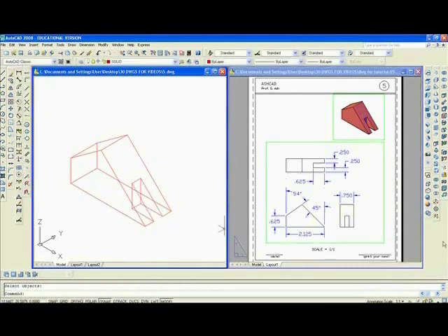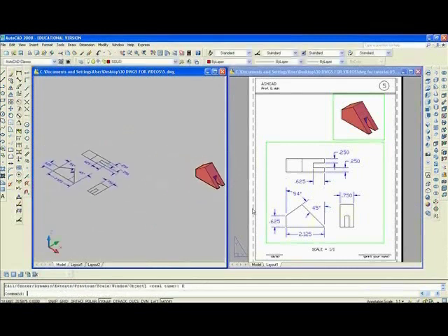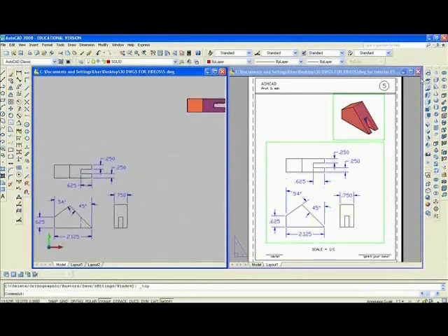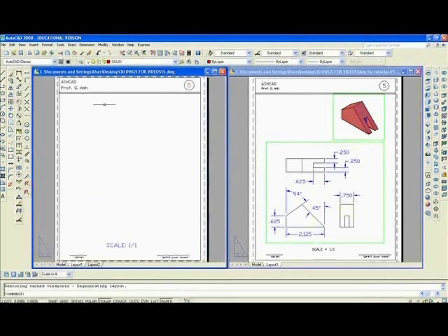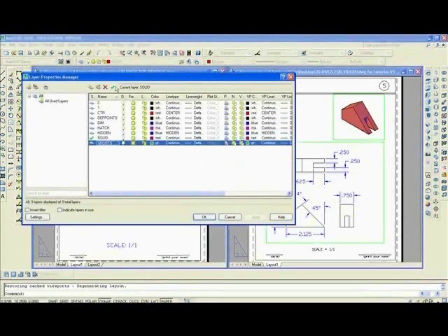And we'll look at it to see if it's okay. It looks fine. So I'm going to Z, enter, E, enter, zoom extents. I'll move into the top view. Then I'll hit the layout button, and I'm going to make layer viewports current.